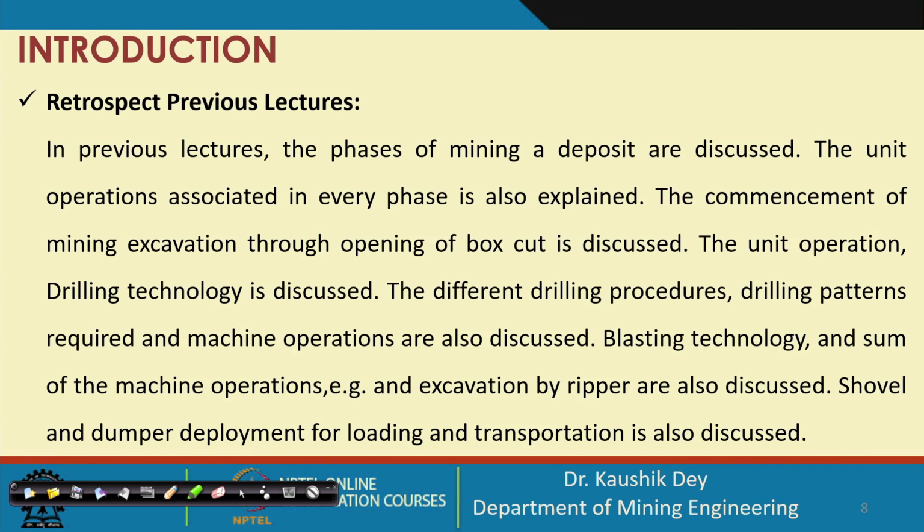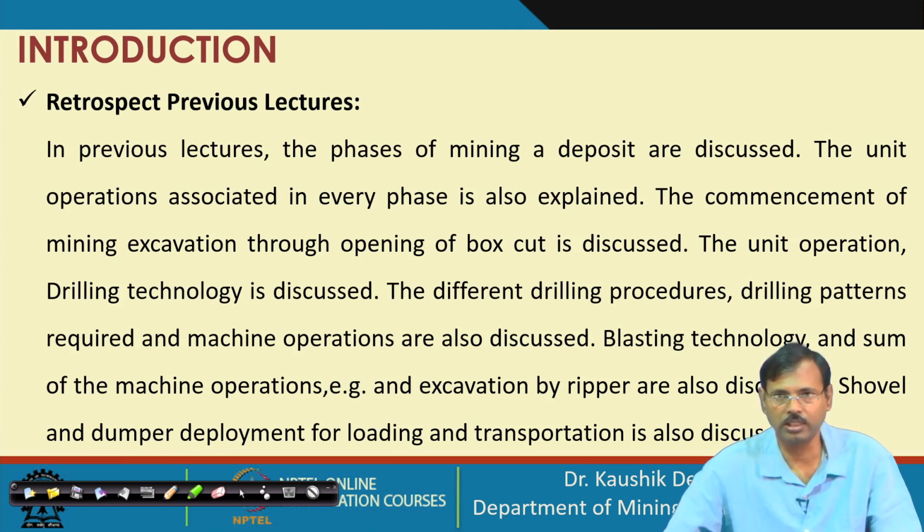We have covered the operation of the surface miner, their methodology, pit layouts, performance analysis and cost analysis. We have discussed the operation of the dragline for direct casting of material, the three modes of operation of the dragline, the extended bench method, direct casting method and side casting method, along with their performance and cost analysis.